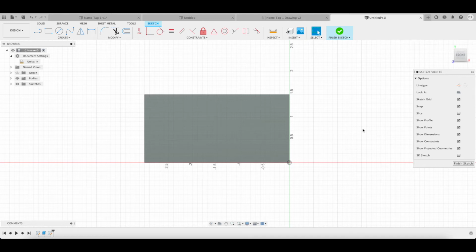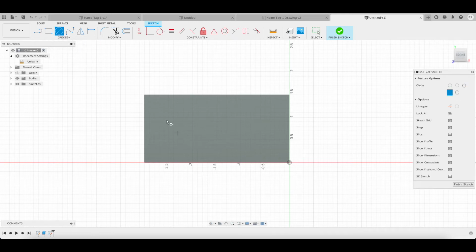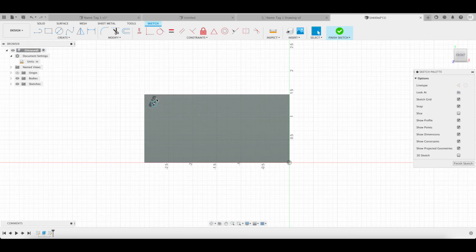And there's the hole tool. I wouldn't recommend the hole tool for this because we're just going all the way through. It's just a circle and it's pretty simple. So I would just use the circle for now. So we're going to go over to the center diameter circle in the toolbar and we're going to set a dimension. All the dimensions for circles in Fusion 360 are in diameter dimensions. So in this case, we want our circle to be 1/8 of an inch, which is 0.125 inches. Or you can also type, because Fusion has a great math catalog, you can type 1/8, which would give you the same dimension.